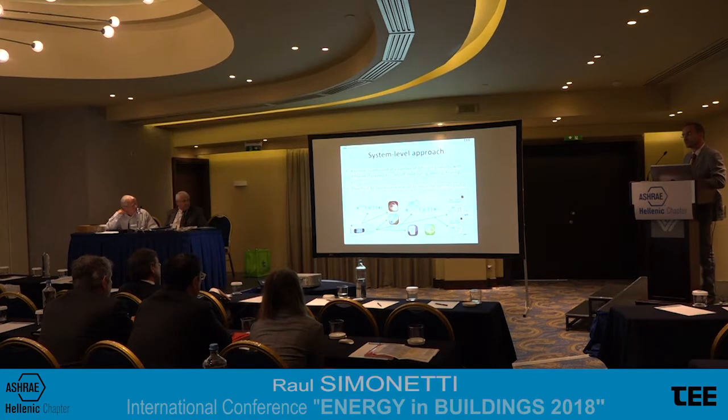Consider also that systems may have different set points. Very often we are focused on humidity and temperature. They are two important set points for many processes, but as a second set point, you can have the minimization of the running cost, which is important for the users. A third set point can be the minimization of the total primary input energy in order to minimize the CO2 generated, so the indirect emissions.